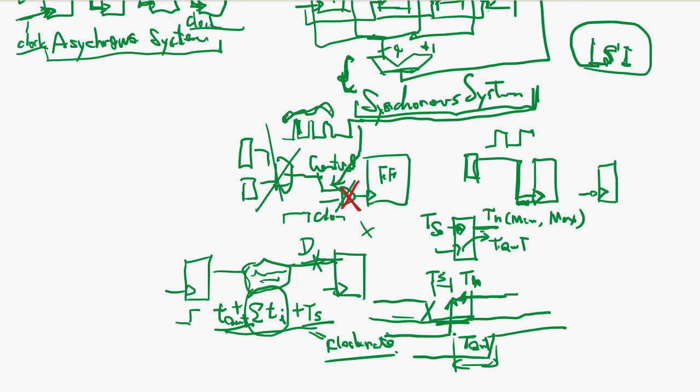Now there is sometimes an issue in this kind of design. If this Q goes to D immediately and the clock comes in, in this case, this T Q out, right? When the clock comes in, data changes, but you cannot change too quick because there is a hold time.